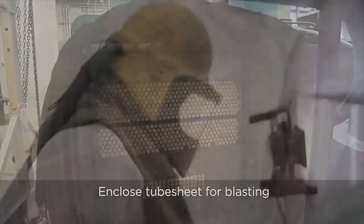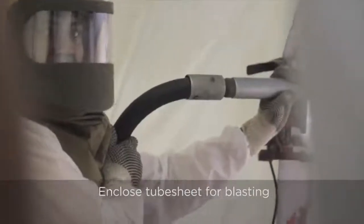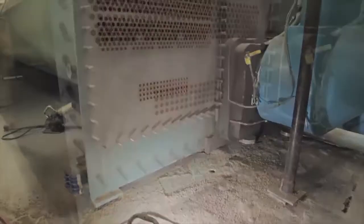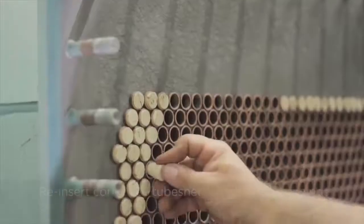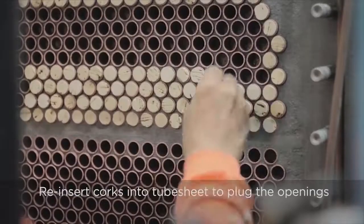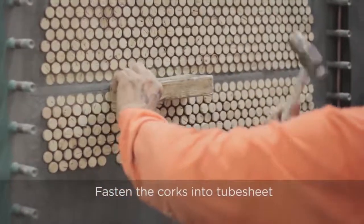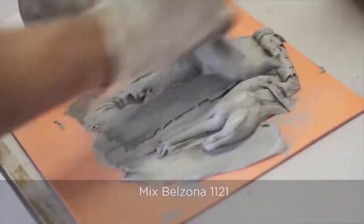So once all your tubes and corks are in and everything's enclosed off and ready for blasting, you start with surface preparation. Ideally, grit blasting is the preferred option because it removes all the corrosion, it cleans the surface really well, and we're looking for a 75 micron profile to the surface. Afterwards, remove those corks and replace them because they would have been slightly damaged from the surface prep process, and refasten the corks back into the tube sheet itself.